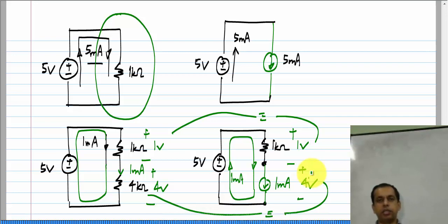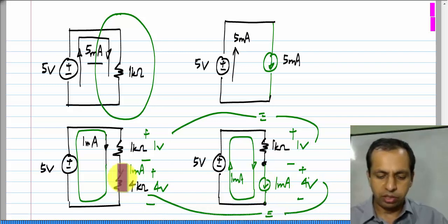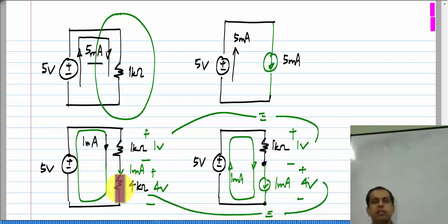Okay. It turns out that you can also back substitute. In this case, in place of a resistor, I substituted a current source. Now, you can also go backwards. You can substitute a current source with a resistor subject to some conditions, and that helps in deriving new circuits, because sometimes it is more cumbersome to realize current sources, but you could in many cases realize the same functionality replacing the current source with a resistor. Okay.